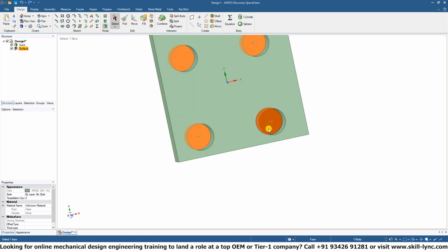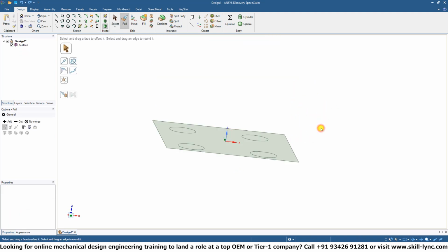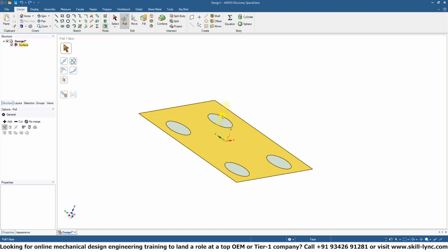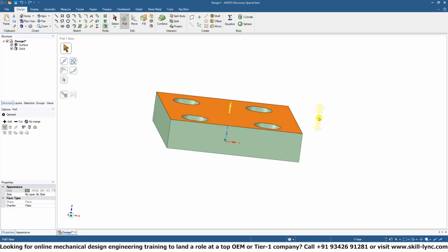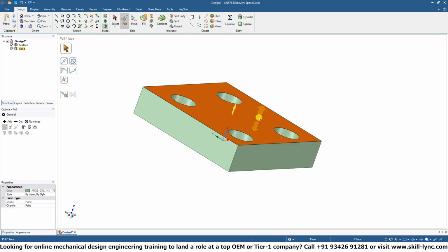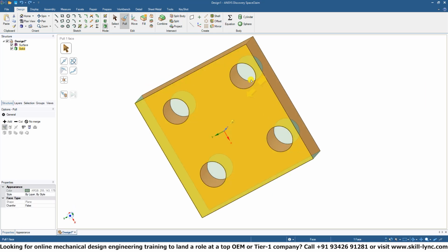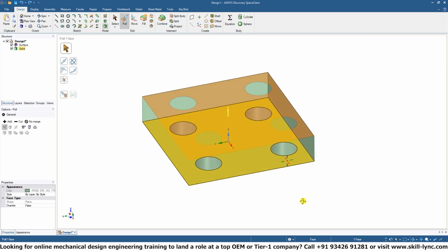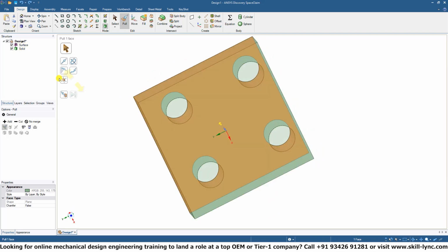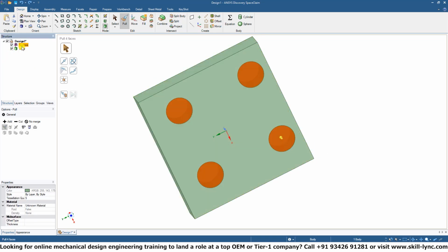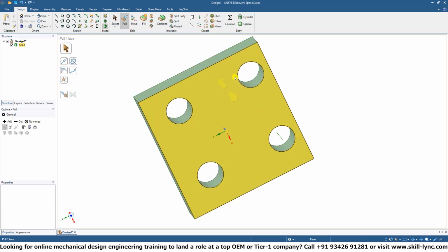That was defined initially when we are doing the pull. If I go back another step, this is a whole surface area that was created when we entered 3D mode. After we pulled this section of the model out, we're still left with this surface area, which is not technically a hole. To get rid of that, you can simply select that surface area and hit delete, and there you go. It doesn't exist anymore, it's simply a hole.